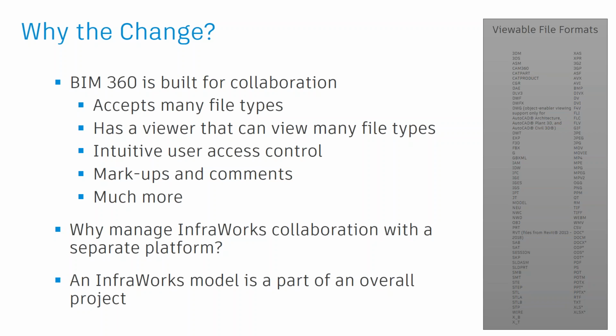The same is true of DWG, RVT, and a whole bunch of file formats that I had to shrink down to really small font to show you on the right side of the screen there. I grabbed that out of the help. These are all the different file formats that you can view right in the BIM 360 environment. So that's really important. The way that you control user access, I think, is very intuitive. It's also very granular. You can go folder by folder and pick out specific individuals that you want to have access to that folder and how much access, what can they actually do in that folder when they get there.